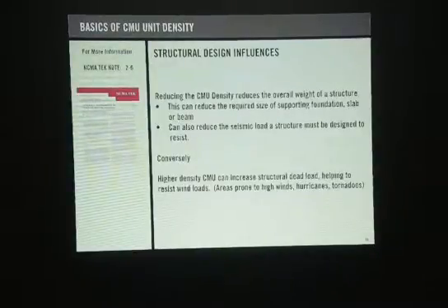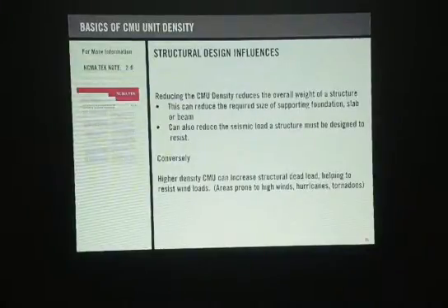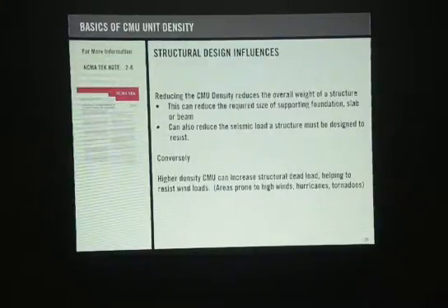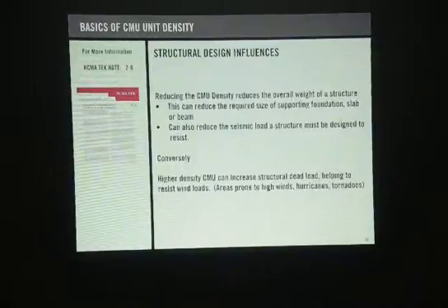Next week I'm going downtown to see the architect who's working on the soccer stadium. For the soccer stadium, they asked to have a water repellent product, an anti-graffiti product as a second choice, and then a third having higher solids, but a solvent-based product that complies with South Coast Air Quality Management District, which means it has to be 100 grams per liter. All three of them are going to be applied side by side, a third and a third and a third. What happens with all of them is they will darken the surface.